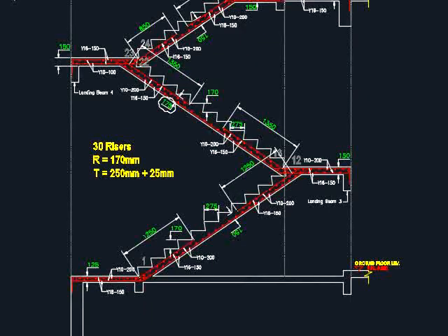The longer the effective span, the more critical it will be, which most likely requires a thicker staircase to ensure it passes the moment resistance as well as its deflections are within the limits, which in this case, because the span here is the longest, the staircase here is the thickest.